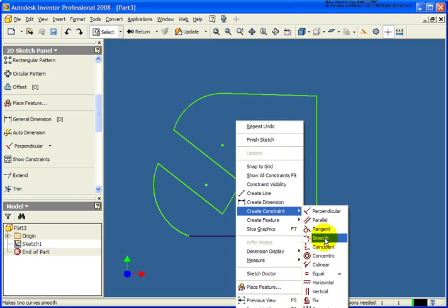And that's going to be smooth. What smooth is going to allow us to do is actually go back and select a spline and another, either another spline or an arc segment or another line, and it will be a constant smoothness in between the given segments here. We'll talk about that later in another lesson. The next one is a coincident constraint, and a coincident constraint is going to be that 2 points touch.